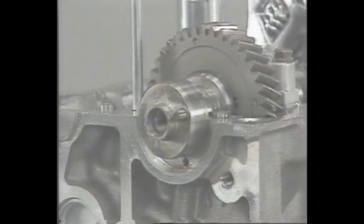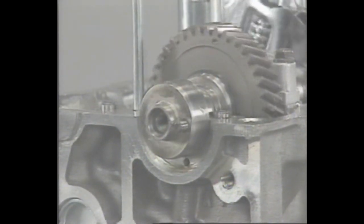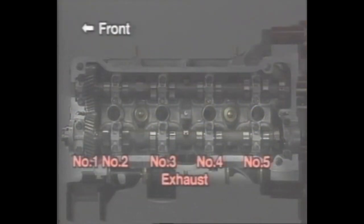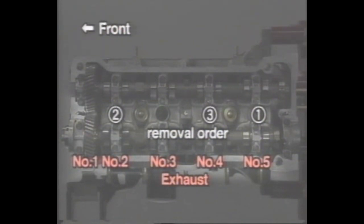Turn the exhaust camshaft so that its knock pin comes to the position shown, allowing the number 1 and number 3 cam lobes to push their valve lifters evenly. Remove the exhaust camshaft bearing caps in this order: number 5, number 2, number 4, and number 3.